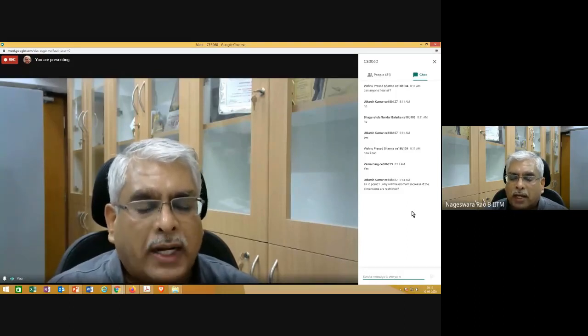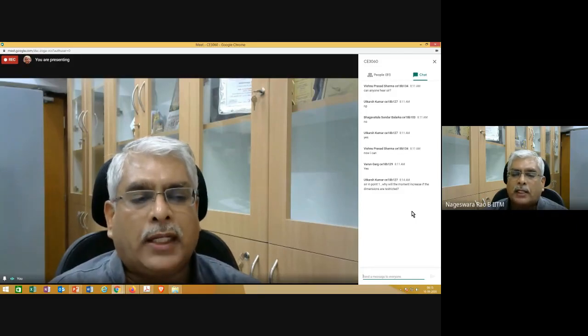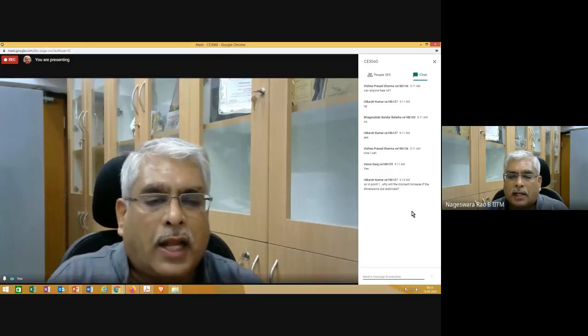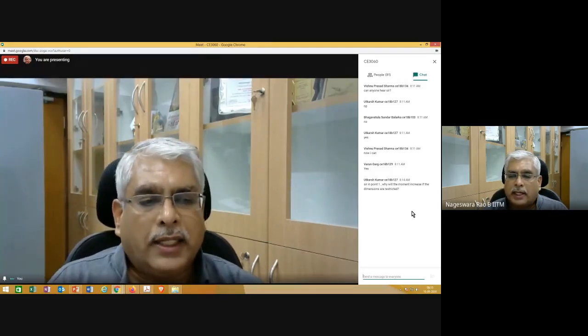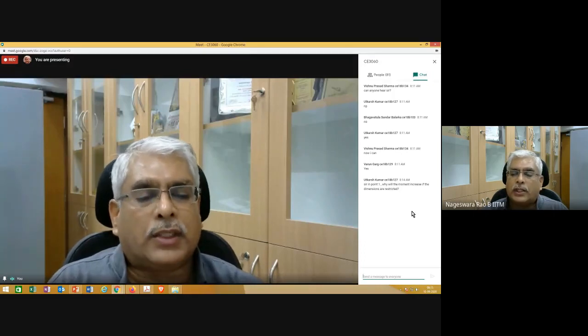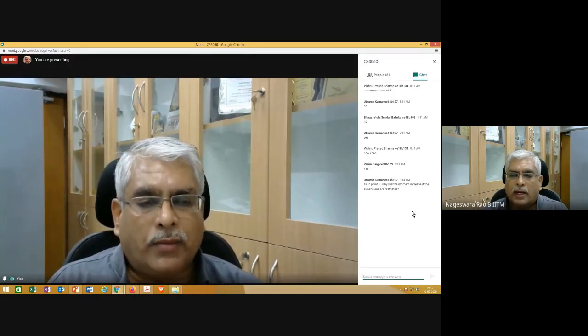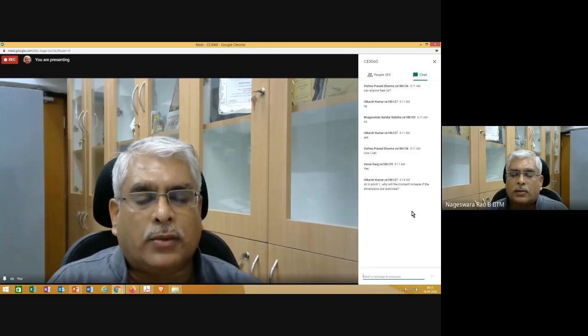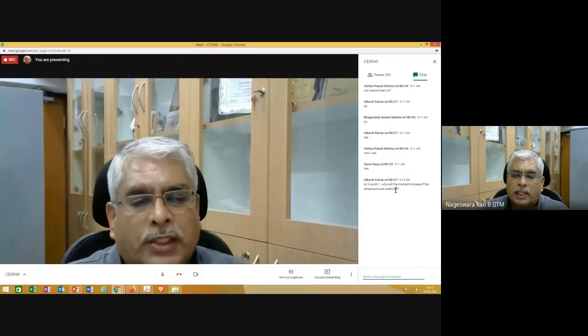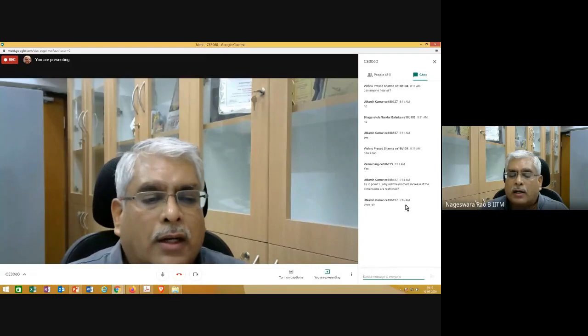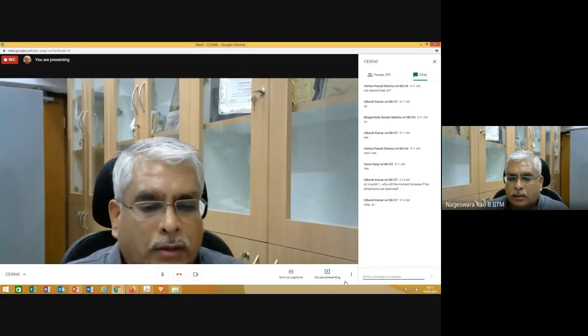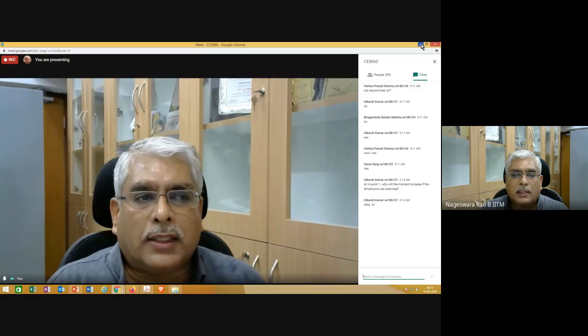So it's not the moment. The applied moment is 150. Please note that in all the examples, the applied moment or the targeted moment carrying capacity is taken as 150,000 Newton meter. Whatever moment this beam has to resist remains the same, but the moment carrying capacity of the beam reduces when the depth is reduced. I think now you understood it. So let's go further.